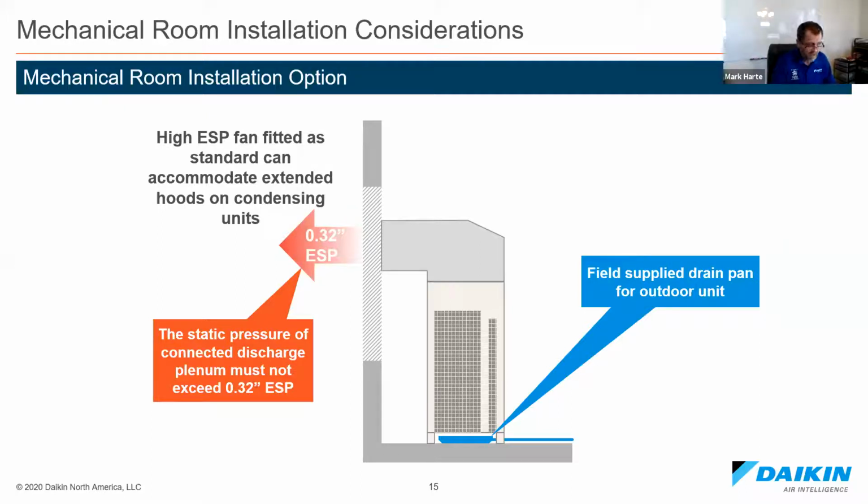There's two types of field settings. We're going to talk about them. One from the indoor remote controls and one from the outdoor unit. The difference would be the ones you do with the indoor remote controls affect the fan coil or indoor units that are connected to that one controller. We can hook up to 16 indoor units to one controller if need be. If you do any field setting from the outdoor unit, it will be on the printed circuit board outside, and I'm going to show you the buttons in a little while. That affects the whole system. So that's the difference between the two field settings.